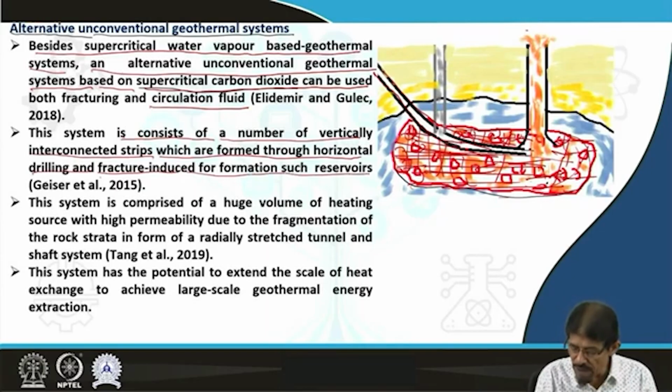In this way, we are going to create tunnel type structures full of rock fragments with enhanced permeability that provide space for the movement of fluid, and the injection of supercritical carbon dioxide through the horizontal approach is going to facilitate the extraction of geothermal energy.